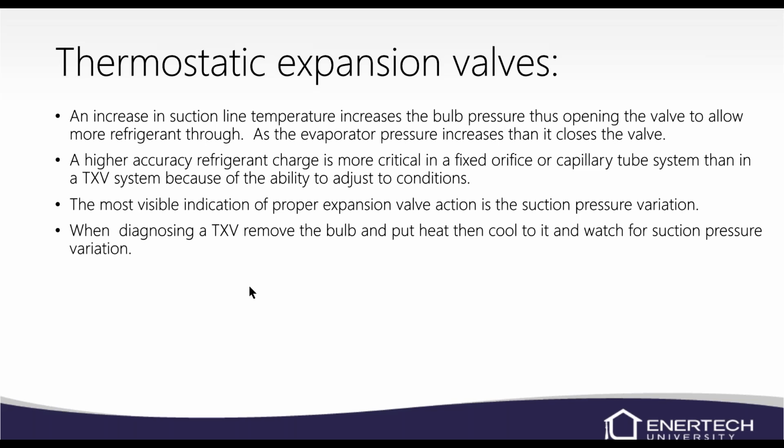Basically, the easiest way to diagnose a TXV is to remove the bulb, and you can warm it up with the compressor that's sitting right there, or you can put it in your hand and warm it up. Then get a glass of ice water, cool it down, and watch for your suction pressure variation. It should move about 5 to 10 psi.